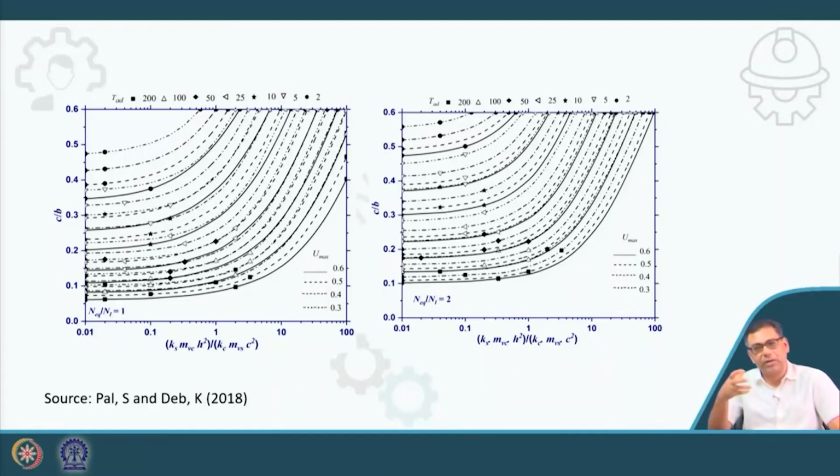You can incorporate the clogging effect also, but here the idea is that we will incorporate the other effects, because we cannot neglect them. The permeability of the stone column we have to consider, the stiffness of the stone column we have to consider, and then the smear effect, that also we cannot prevent.